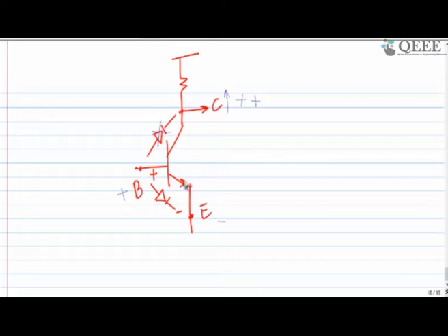And whenever you make this particular junction forward biased, the voltage drop across the PN junction will be the cut-in voltage of the diode, and that may be 0.6 to 0.7 volt. Let's write down 0.65 volt, this is the nominal value, right? You may keep 0.7 also, it's not a big problem, but this is given in other books and other people are following it, so I kept 0.65.